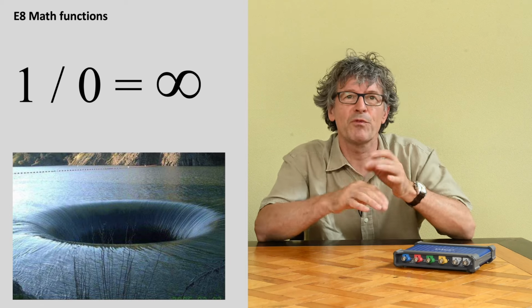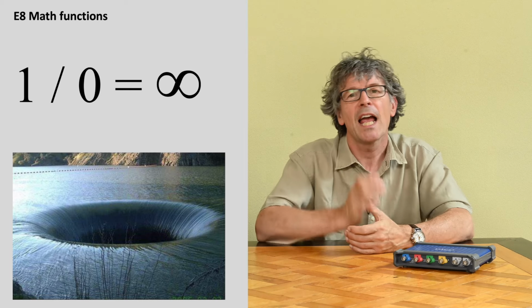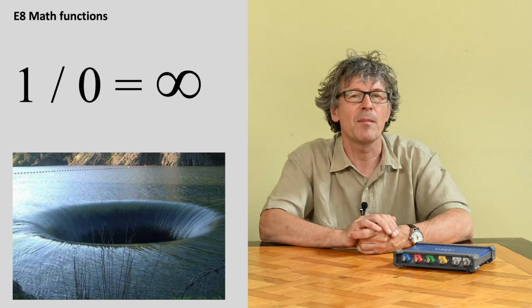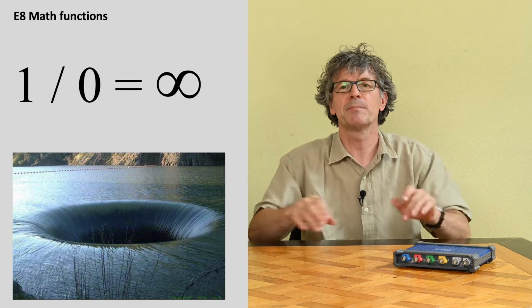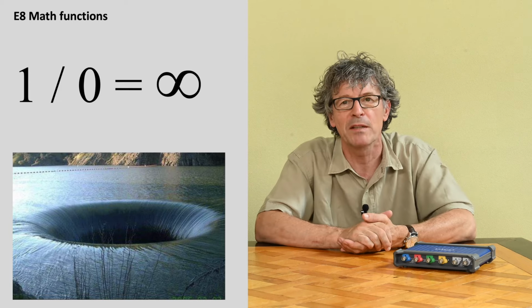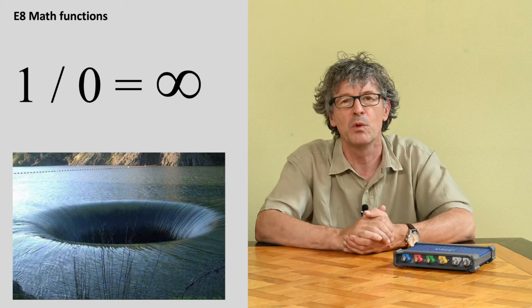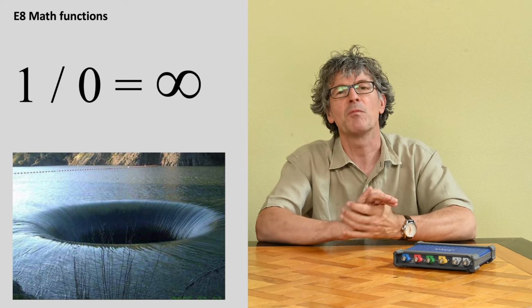And if you divide something by a very small number, then the outcome is going to be a very high number. And that is typically what we do not want in daily measurement practice. Very high numbers, like in the tens of thousands or hundreds of thousands, are problematic because they will mask the type of waveform that we're typically interested in looking at, or even block doing our work altogether. So ideally, you would have it kept off somewhere at some point.